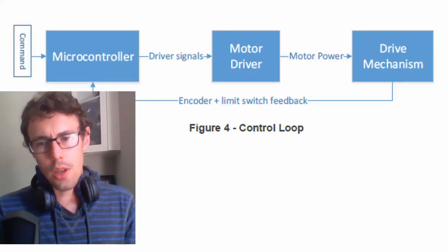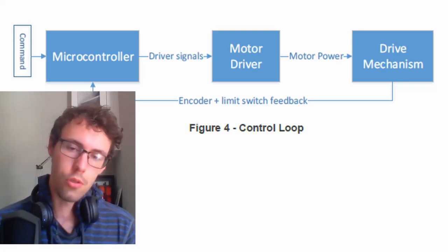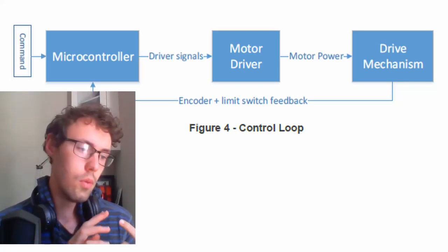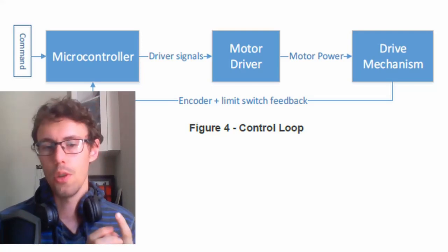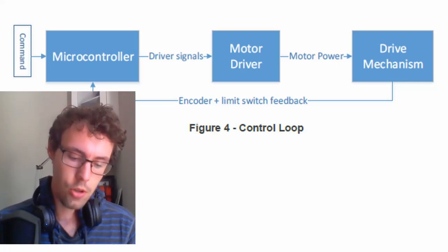Then you have to choose a motor driver, so you know how much current your motor is going to pull because you chose the motor, and you know what kind of torque it has to output, and therefore you can equate what the motor current pull should be, and you can then choose the right motor driver that will receive a PWM signal from the microcontroller, and the transistors in it will convert that into a much stronger current for the motor to be driven at.